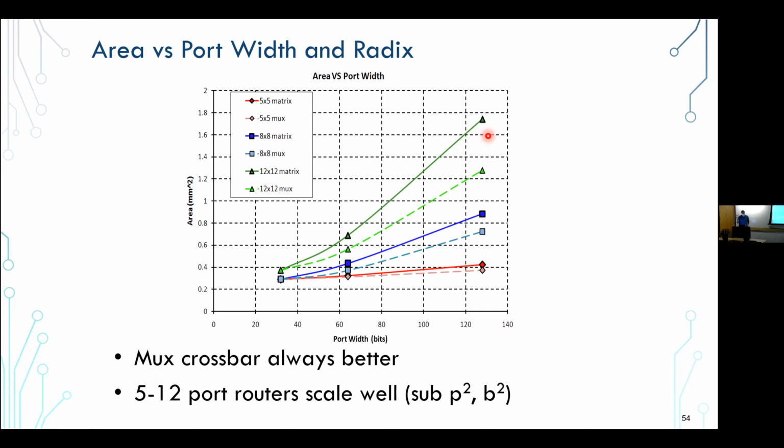With an output mux crossbar, you can optimize that, run denser wires, and then locally stage your logic so that you can optimize the overall area. So you can kind of see that, but you can see it more dominantly for wider buses. Right? If you have only a few wires running across per port, then it's not such a big deal. You still have the area available to put the logic.